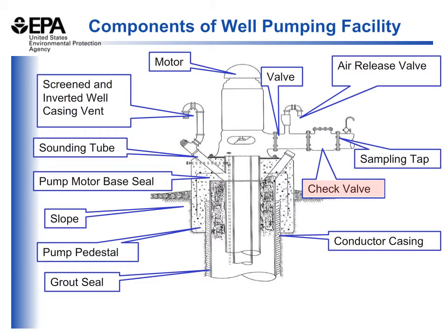In terms of operation and maintenance, there's not a lot of work that needs to be done on these different components of the system. The extent of operation and maintenance that's needed for the well pump will depend on the type of pump you're using, whether it's one with the motor at the surface or it's a fully submersible pump. The propellers on these systems need to be maintained on an occasional basis, and the motor and the moving parts within the motor need to be maintained and oiled as necessary. And the engine components in the motor need to be maintained per the manufacturer's instructions.